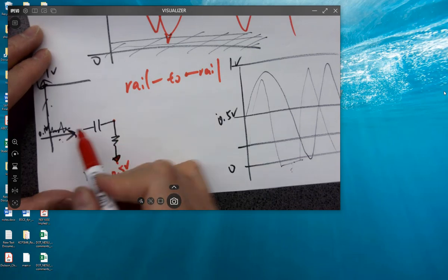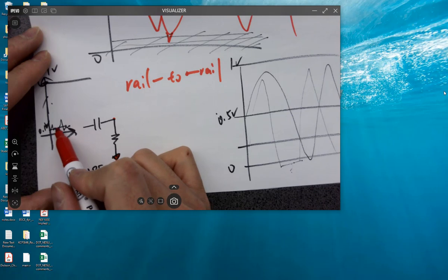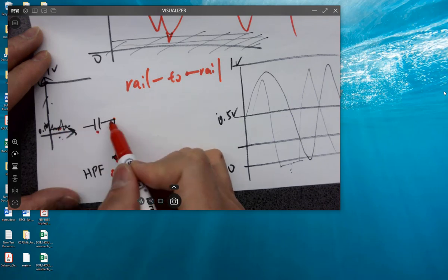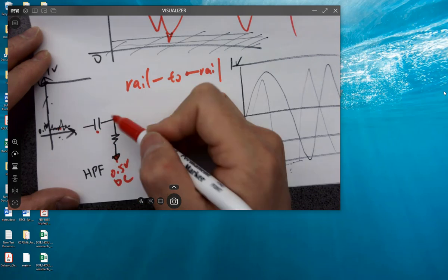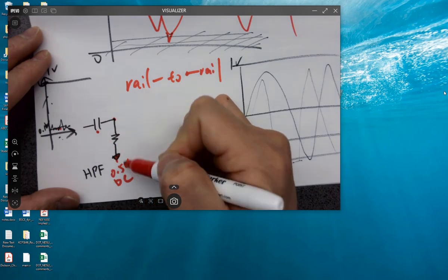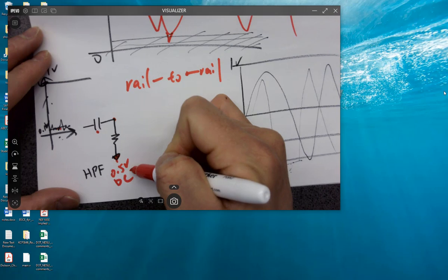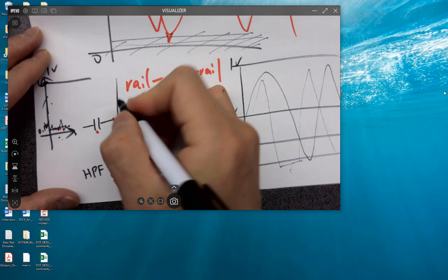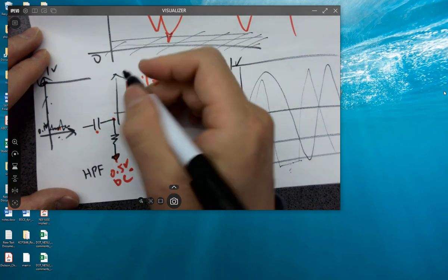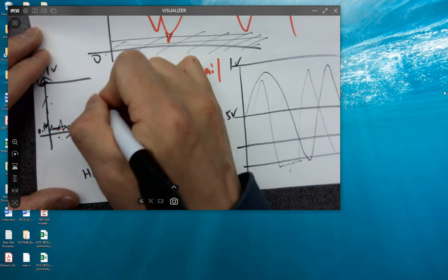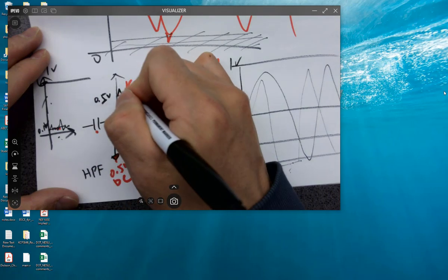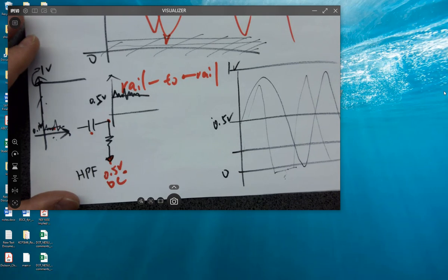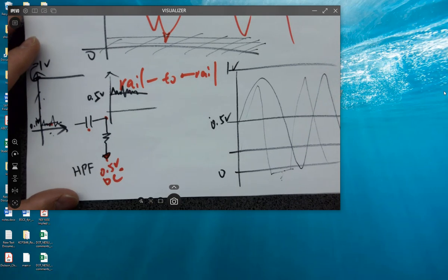The DC offset of the signal is getting blocked by the capacitor, but AC is able to pass. So you are getting 0 DC offset over here, and then you superimpose a 0.5 DC voltage onto it. It's going to lift the signal to 0.5 volts. So eventually your output over here ideally should be 0.5 volts with this AC signal on it. Make sense? That's the first step.